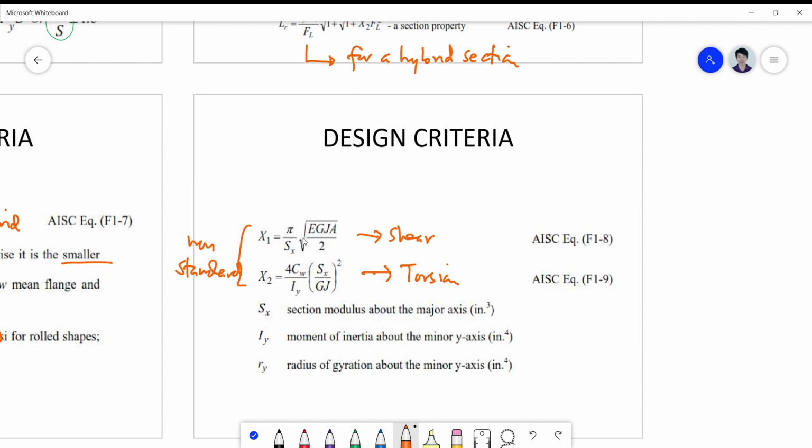So you can compute it on this basis. Of course, the units must be consistent for you to be able to find the right value for your moment strength. You have to come up with a consistent unit. And if we are using an English unit, this must have something to do with inch-kip unit.